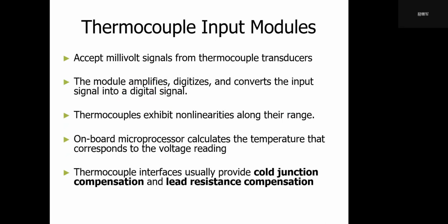The temperature module accepts millivolt signals from thermocouple transducers. The module amplifies, digitizes, and converts the input signal into a digital signal. Thermocouples exhibit non-linearities along their range.